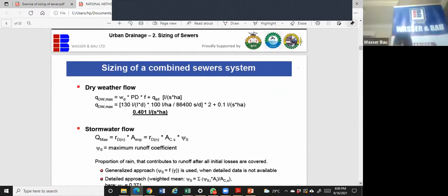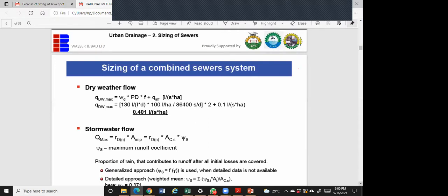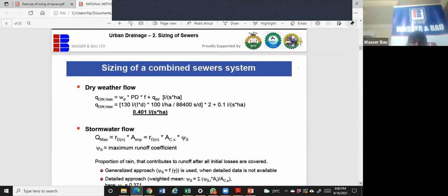For the stormwater, yes? Please, I want to ask, is there any guidance on the population density? Yes, there's guidance. Number one, if it's a built-up area, you use empirical evidence. Say, how many people per household, multiplied by the number of households. If you come to a street and there are 3-bedroom bungalows, like what we did in water design, if there are 100 bungalows, and if it's a mini estate, let's say each household is about 10 persons, then 10 persons times 100 houses in the estate becomes 1,000. So your population density becomes 1,000 per capita.